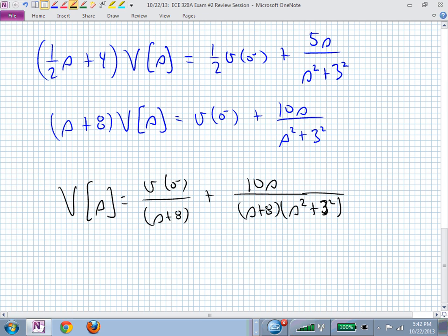And now you can really write down, I hope, by inspection, the structure of little v of t. You could put these two terms over a common denominator, but this one is going to give you what kind of an expression in the time domain? An exponential, and what's going to be in that exponential. So when I ask for the structure, I want you to give me that exponential. I don't need you to give me the coefficient in front of it, but I do want the exponential terms and the frequencies in the cosines.